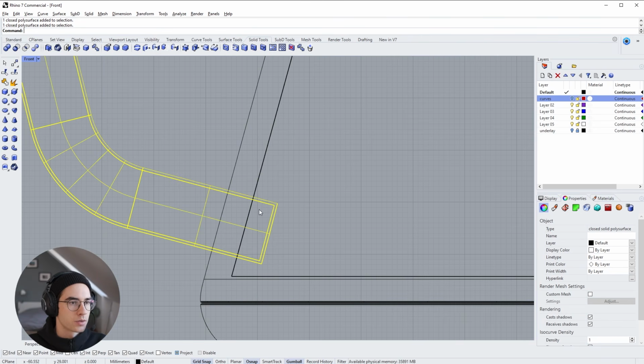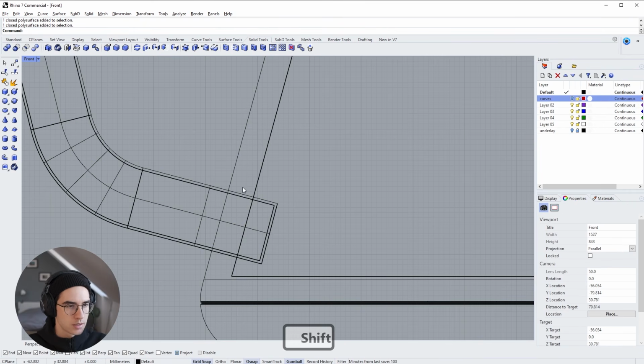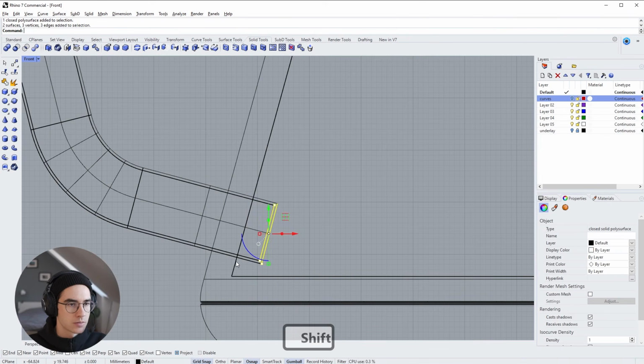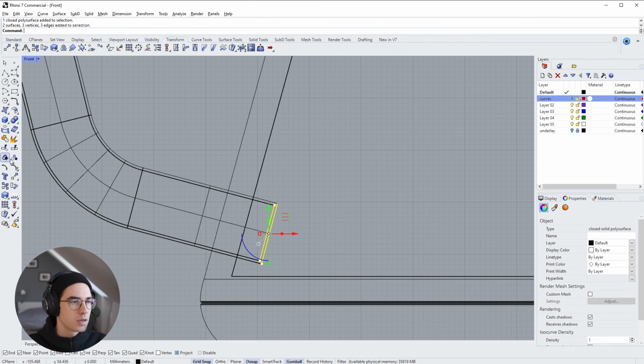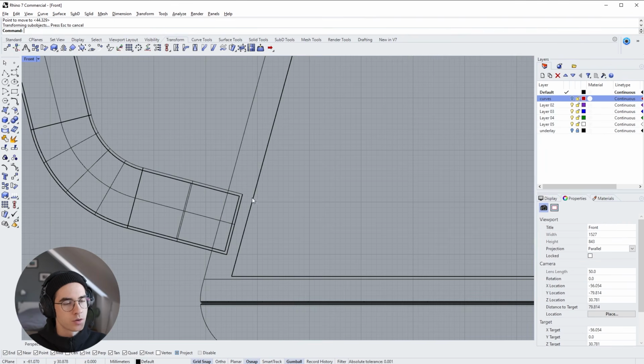So what you can do, and that's a nice trick I'm trying to use less often, but it's sometimes just easier to do. Hold down Control and Shift at the same time and drag around those edges. And this will just select anything that's inside your selection. So in this case, these points and these lines. And now we can go to Transform and Move tool and move these along this line upwards into the volume of the can. We could have made a line and cut the rest off, but this just is a bit easier, quicker in the end.